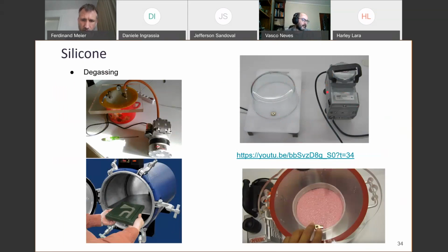Of course, it's better like this pump you see down here. If you Google for two-stage vacuum pump, you will find some machines very similar to this one. They're quite cheap. There's a one-stage and a two-stage variant. You should definitely get the two-stage one. You can buy it in conjunction with a special cooking pot for degassing, but you could also make it a lot cheaper just by using another pot. Like I bought this huge